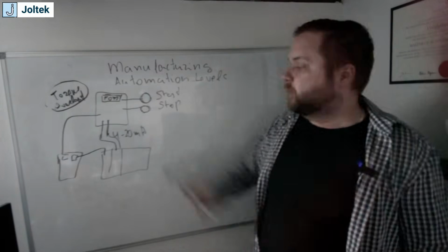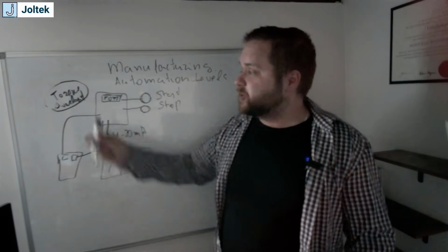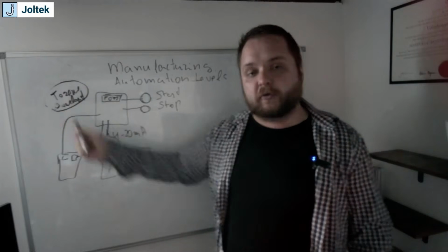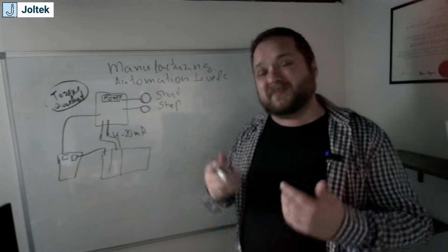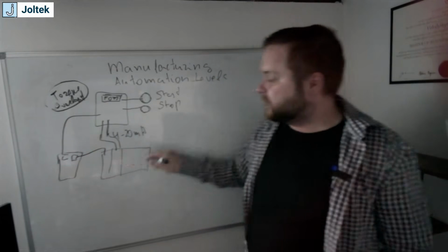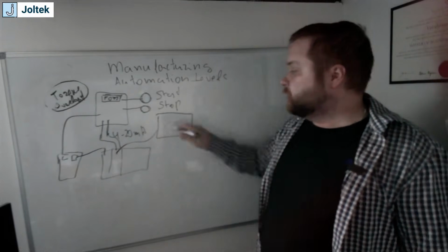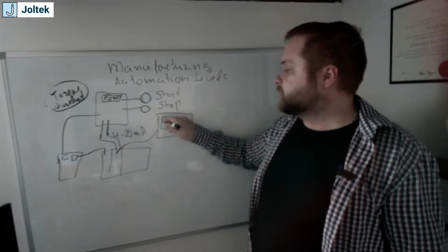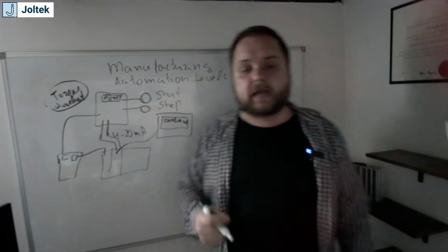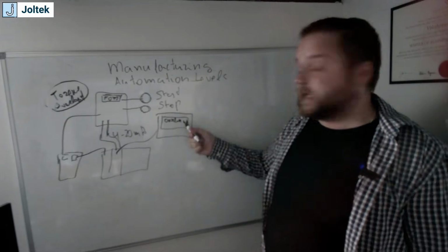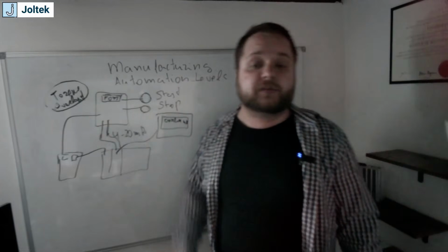So why am I saying all this? When you're connected over current, or if you're connected over start and stop digital inputs, the chances of you realizing that it's a torque overload and then fixing that issue is going to be much longer, or the response time is going to be much longer than if I'm connected over Ethernet. I can then send this over to an HMI screen with an alarm that will automatically notify the operator, right, within a screen that says overload motor 12, for example. And so I can add a lot of descriptions. And in this case, it's going to take, for example, 10 minutes to fix. And if you were using current, it's going to take 30 minutes to fix.